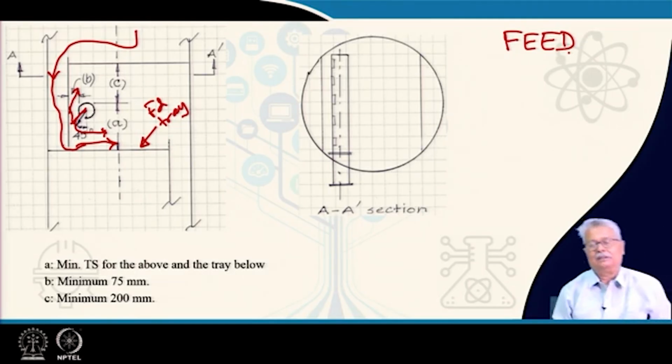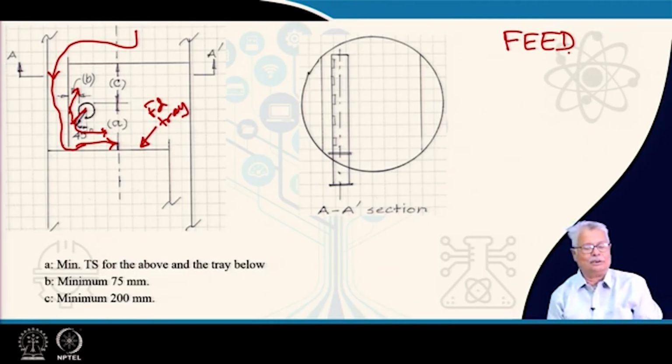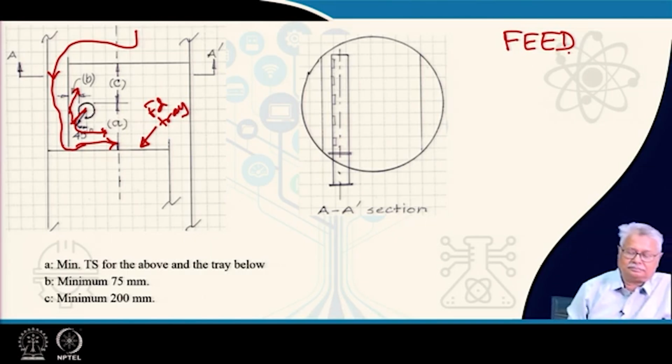That means the other side of your downcomer plate, or downcomer skirt or downcomer apron, whatever you may call it, acts as a splash baffle. The splash hits it and the vapor and the liquid separate over there. Do not confuse this with the splash baffle term, which we are not going to cover here, but if you are interested, you can discuss it later on.